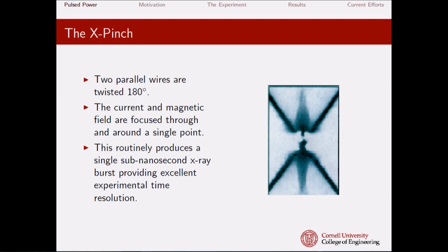The problem with this design, though, is that as soon as that X-ray burst goes off, it tends to destroy the X-pinch. And you leave the machine with an open circuit in its load region. It's still trying to drive current through what it sees as an inductive load. So you get a lot of electrons flying through a vacuum gap that produce a shower of X-rays that you really don't want to deal with.